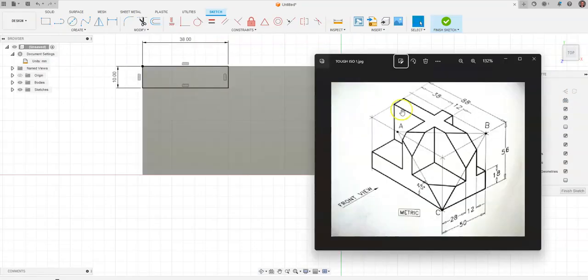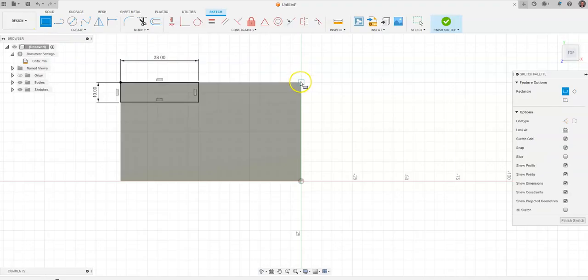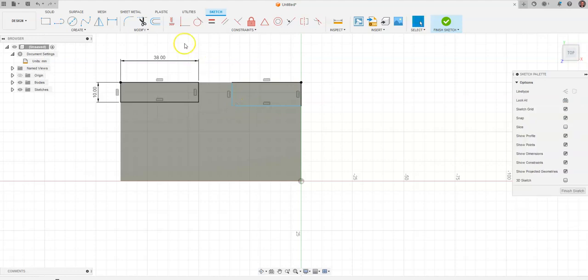Now while we're still at the back, we can see that 38 plus 12 is 50, 88 minus 50 is 38. So over here is 38, and the width is going to be the same. Now a way that we can do this is we can snap on our corner, and we're going to drag out, and I'm just going to click and place a rectangle, and I'm going to come up and grab the dimension toolbar, and I'm going to click here and drag up, and I'm just going to tap on the 38, and the D6 means the 6th total dimension that we've placed, and that includes every dimension we placed when making the box. So we're just going to tap on the 38, and that's D6, and also you get the FX for function.